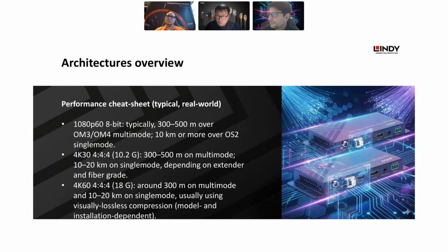The performance sheet for this technology: Full HD, 60 Hz. From 300 meters to 500 meters over multi-mode cable, OM4 or OM3, or 10 kilometers over a single-mode cable. 4K, 60 Hz, 4:4:4, with a bandwidth of 10.2 gigabits, up to 500 meters on a multi-mode cable.